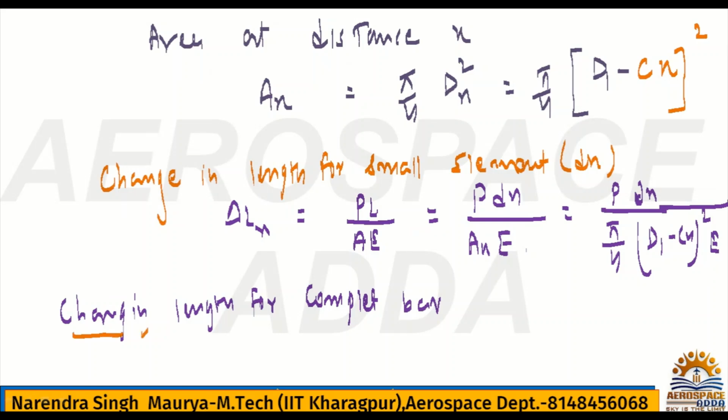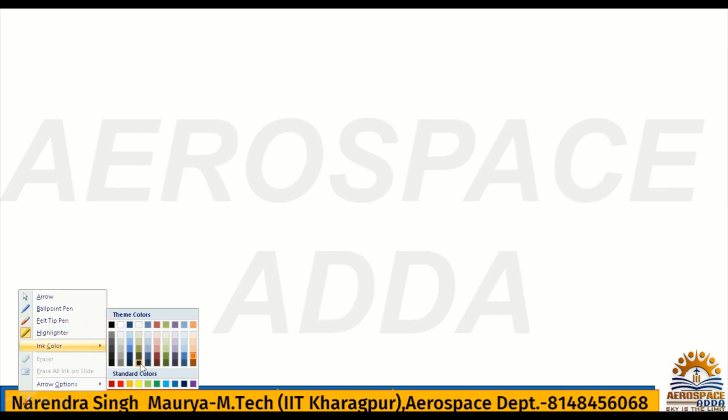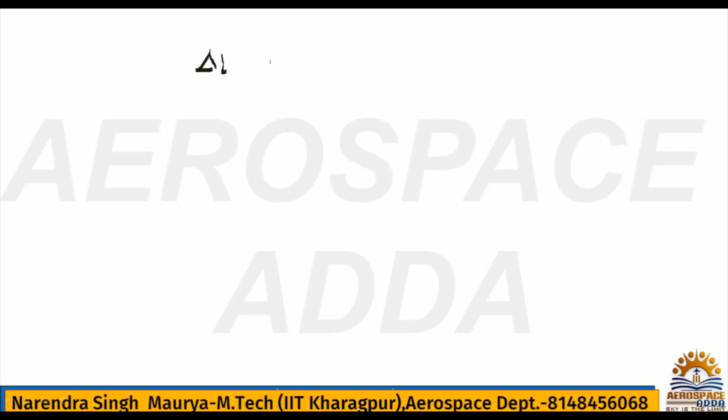Now if you are going to calculate the change in length for the complete bar, then you write delta L, and you calculate it by integrating from 0 to L this delta Lx. If you integrate this delta Lx from 0 to L, then you will get the change in length for the complete bar. That is your job only. This is done now. I will write another step also. Hope this one is clear. Now coming to delta L for the entire bar, the change in length will be integral from 0 to L. P is nothing but, as usual, the load.